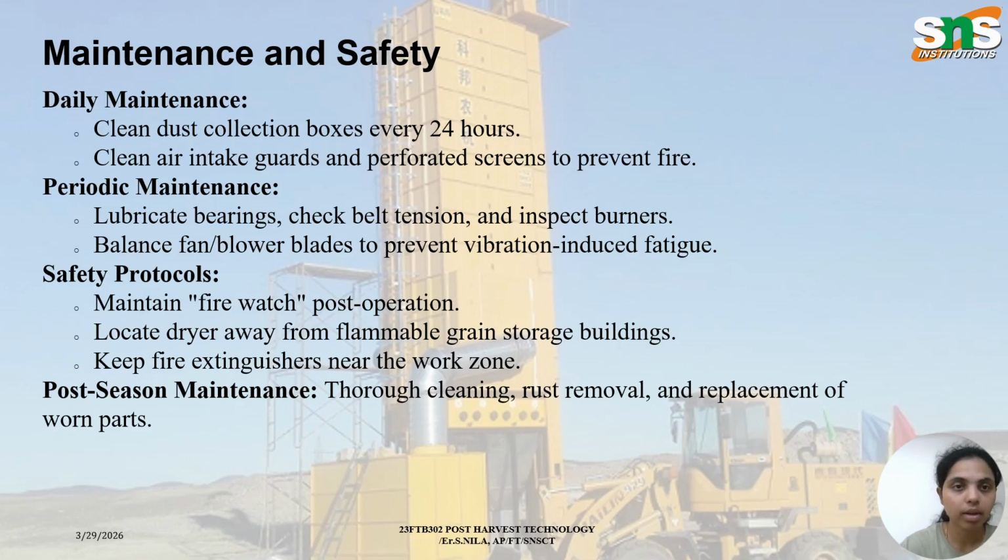We have to consider the maintenance and safety measures too, right? For daily maintenance, they clean dust collection boxes and perforated screens every 24 hours to prevent fire hazards. And periodical maintenance is of course necessary, where they lubricate bearings, check belt tension, inspect burners, and also balance fan blades to avoid vibration.